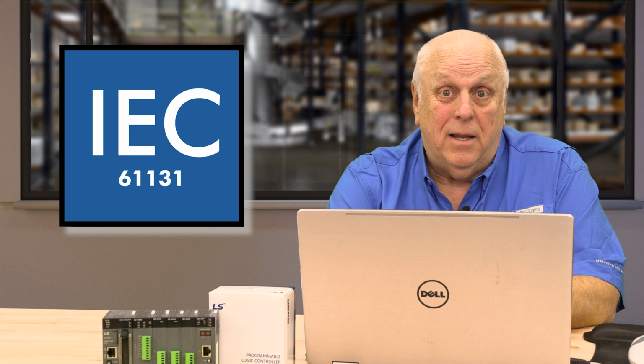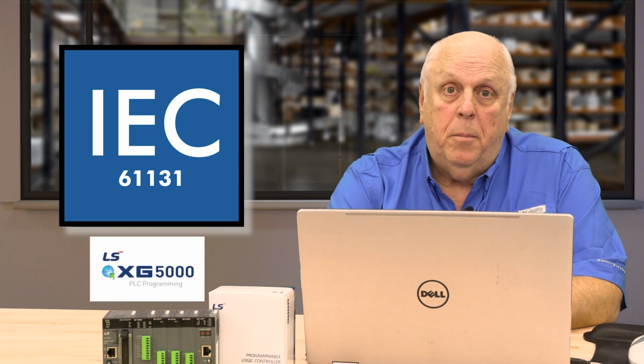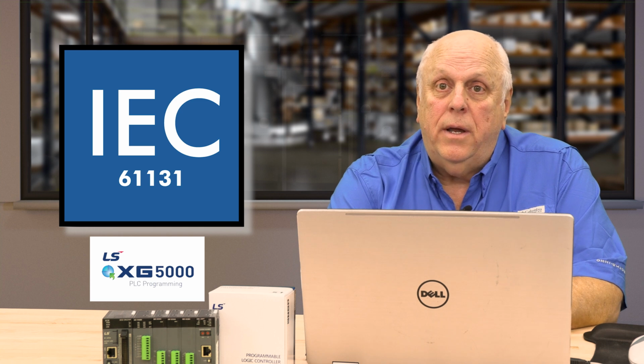Now, the thing you might be aware of is that the vendor has to meet the basic standards to be IEC 1131 compatible, and the LS does. But then you can add on your own things. For example, there's a basic set of instructions IEC requires, but I can add more instructions that are my instructions. So if it meets the basic standard of IEC 1131, they call it IEC 1131 compatible. It may have extended instructions that the manufacturer made for their PLC, but it has the base instructions.